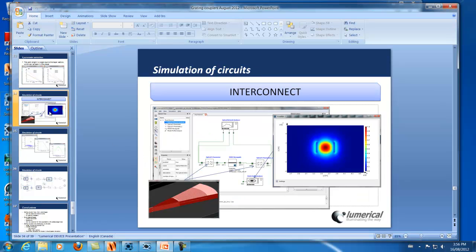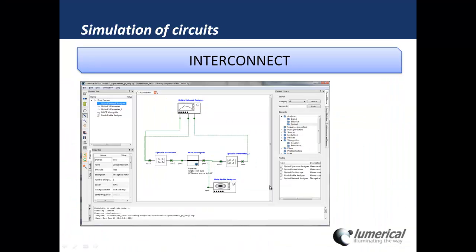Okay, so that's the FDTD and mode simulation. We now have our design. What if we want to actually start simulating how this grating coupler is going to perform in larger scale circuits? And that's where we turn to INTERCONNECT.